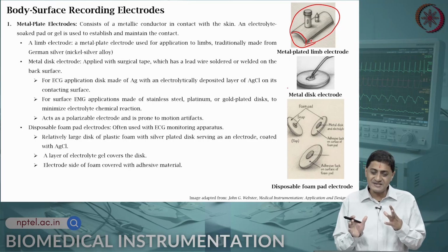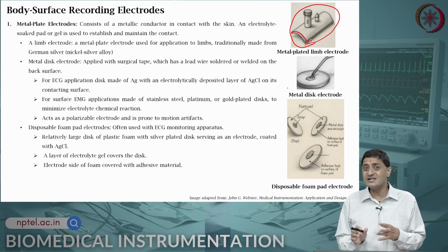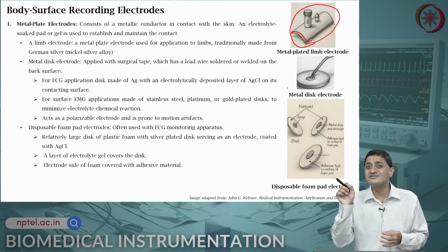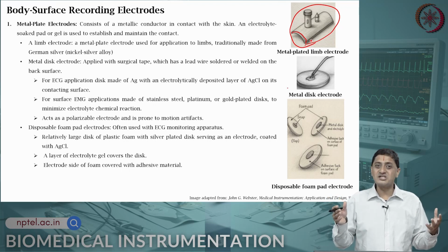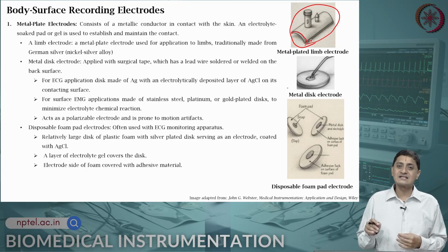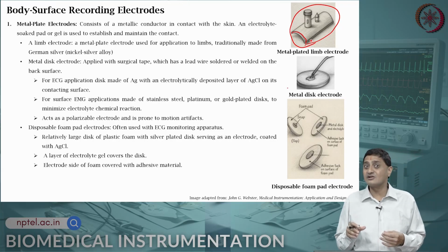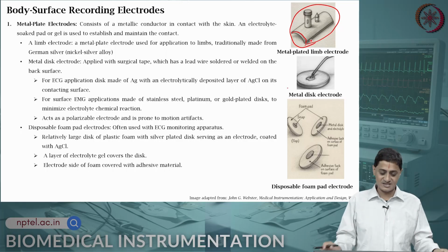Note that it is always a trade off between surface area and impedance. If the surface area is very small, like in the case of the microelectrodes that we looked at, impedance becomes very big, especially in the case of micropipette or glass filled electrodes, and because there are also capacitive effects that come into the picture, which we have discussed in the previous weeks.